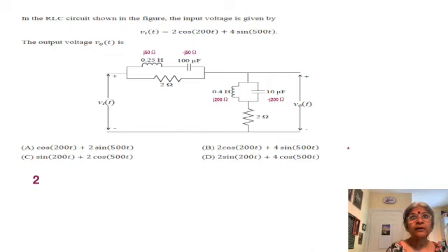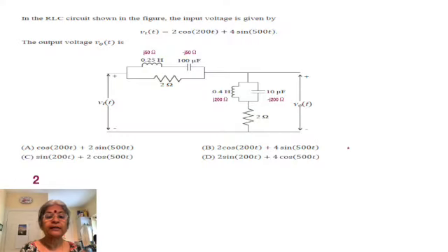Any resistive, inductive, capacitive circuits are going to be linear circuits, whereas diodes and transistors etc. make them non-linear. So if it's a linear circuit, no doubt we can apply superposition in reverse. That is, the source can be split up. So we apply first 2 cos 200t and then we apply 4 sin 500t. The advantage is that now the two omega values can be separated and used.